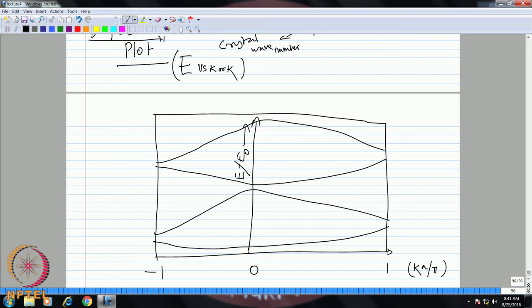Now, these are actually not perfectly continuous, as I said, you have a little bit of discontinuity. So, if you really want to plot them, it will be like this, because your kappa a is also a discrete value. So, really speaking, these are quasi continuous, but nevertheless you can assume them to be some solid line like this. So, you understand. This is how the electron energy levels look for a real structure.